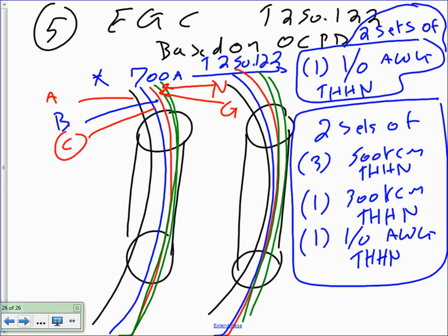Now, do I need a ground if I'm using EMT? No. So that number 1 aught might not be used because we're using the EMT conduit. You only use it if you're using non-metallic conduit. Am I clear about this? And you have to put the equivalent ground conductor with every conduit. That's the rule, every conduit. Even though we really didn't parallel here, if you're paralleling, you have to stick it with every conduit, the same size.